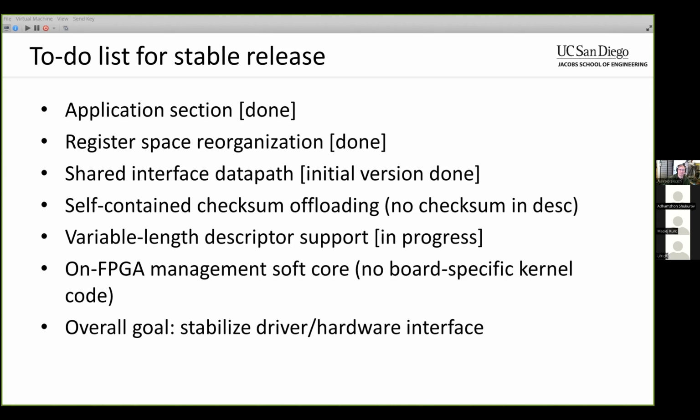Yeah, we actually did another trick, or found out. We usually use the same machine as the source and the sink in our bridging scenario. So just to remember, our test cases have a source PC with a standard NIC, which also acts as a sink, and in between via switch magic, we have our custom card with our MQNIC design, which does layer 2 bridging between two ports of the card. And for this setup, we are using the sink and the source on the same machine.